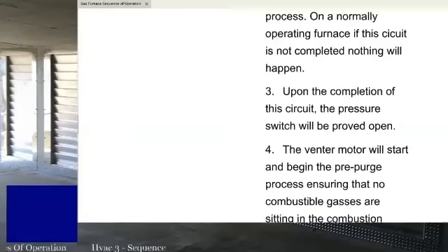Yeah, it has those little tubes attached to it, right? Yep. So on most residential equipment and even on a lot of your commercial, you always have to prove that the inducer motor is running before anything else can happen. Okay, so it has to say, okay, the draft motor is working. Because if the draft motor is not working, everything's going to overheat like hell and it's not going to vent properly.